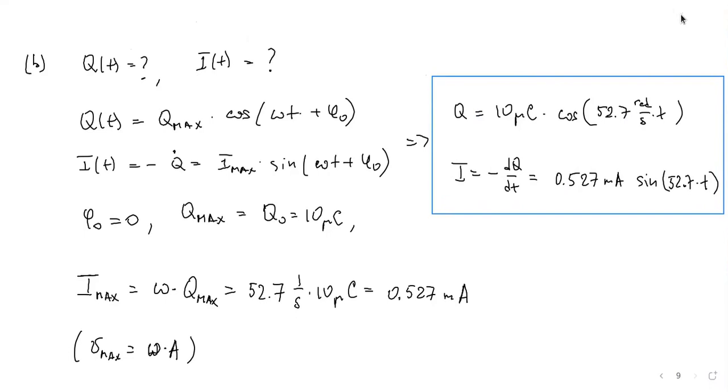How do you like it? Of course, we can find kinetic energy, I mean energy inside inductor as a function of time. I just have to make it square the current multiplied by inductance and over 2. I also can find the potential energy as a function of time, or energy inside the capacitor, charge square over 2C.